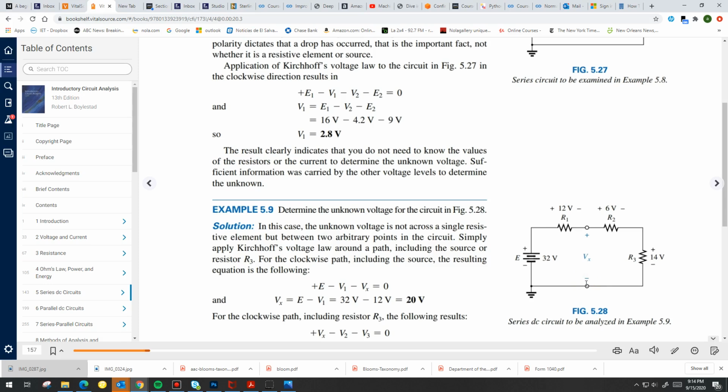Okay. Well, it will really measure the voltage on either side, right? Meaning that the voltage that you will measure will be the voltage from this point across R1 across the source. That's the voltage it will measure. But it will also measure the voltage across R2 and R3. It's the same voltage, right? It's the same voltage because it's the same 2 points related to the circuit.